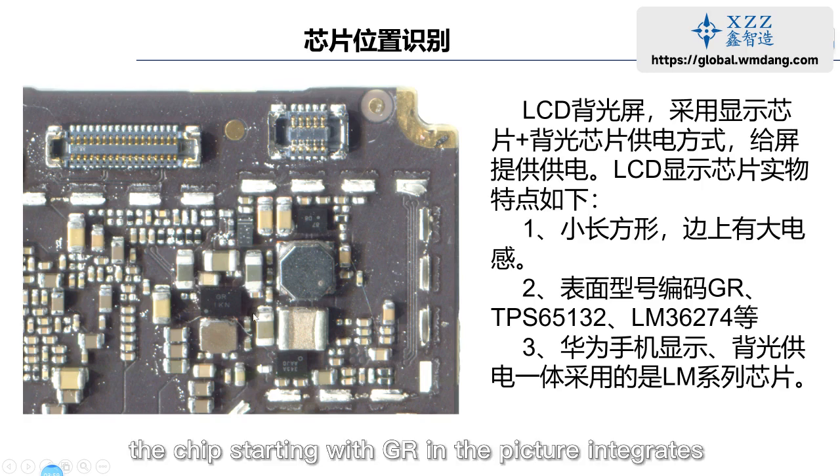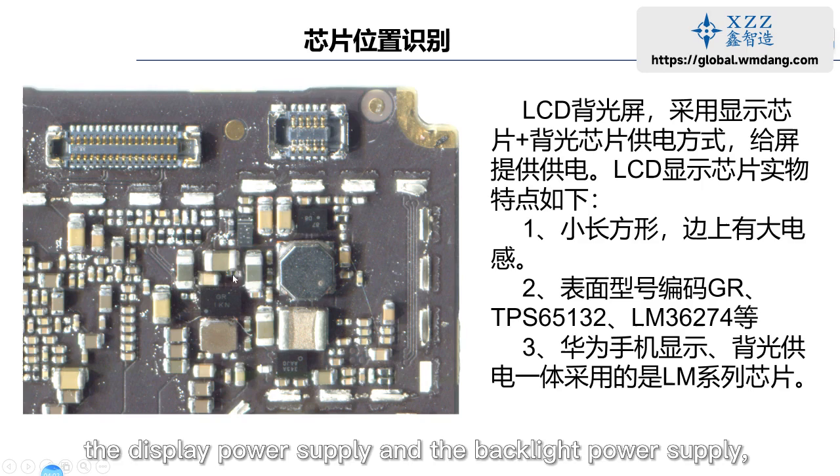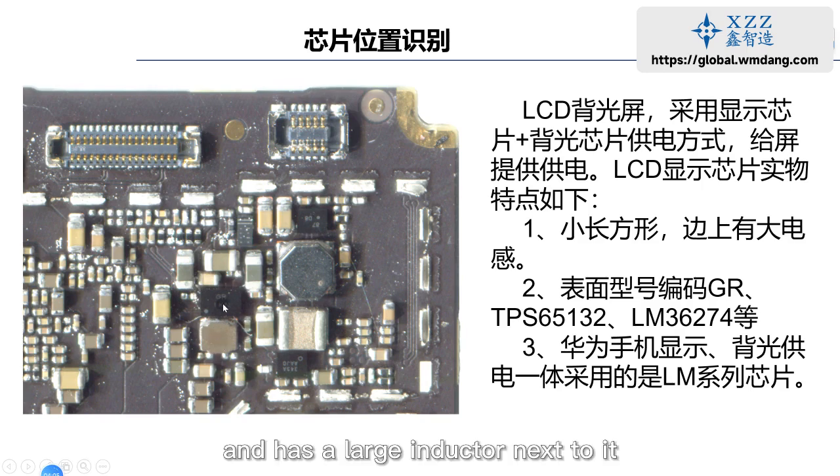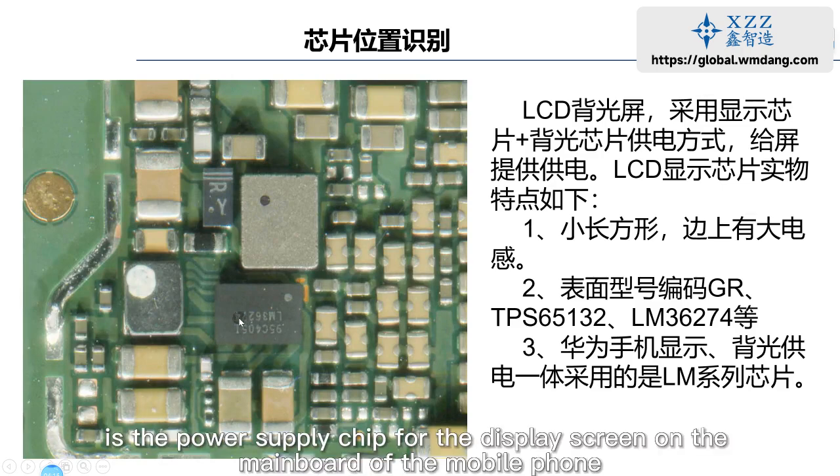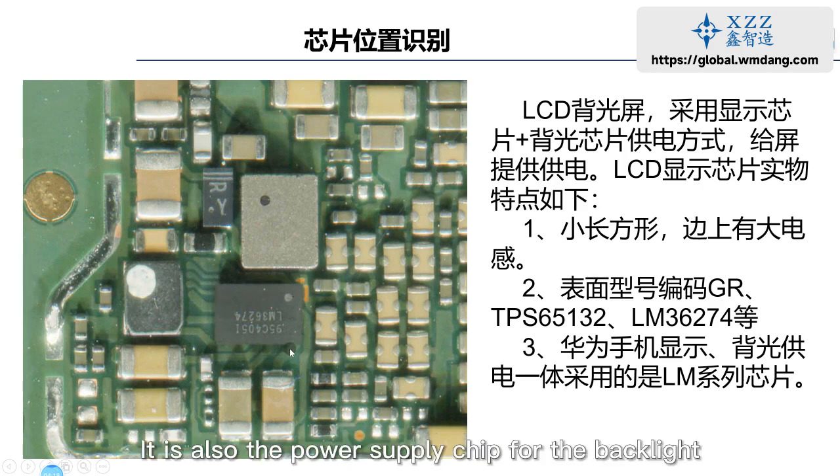For example, the chip starting with GR in the picture integrates the display power supply and the backlight power supply, and has a large inductor next to it. This chip, LM36274, is the power supply chip for the display screen on the mainboard of the mobile phone. It is also the power supply chip for the backlight. There is a large inductor next to it and a diode.